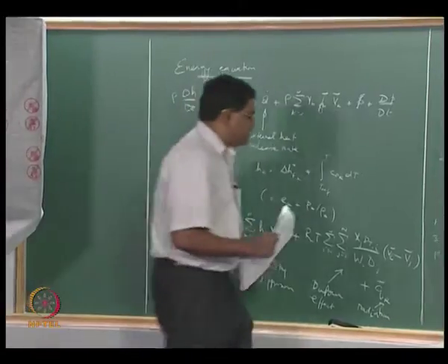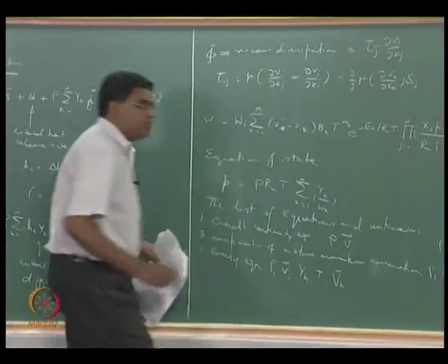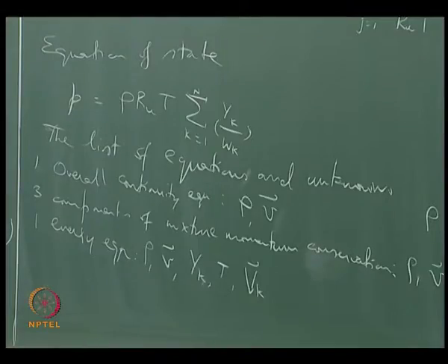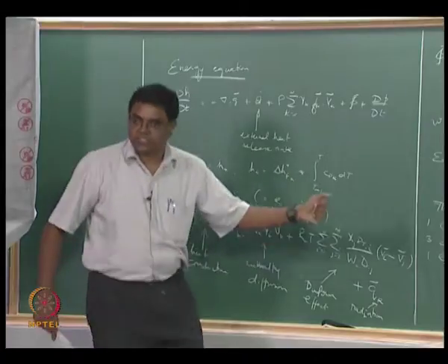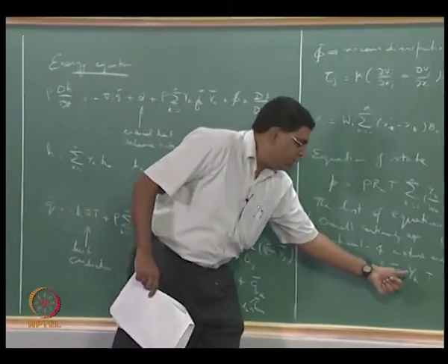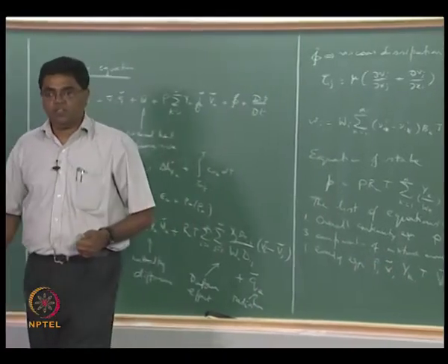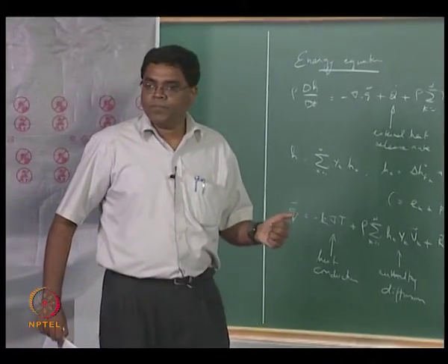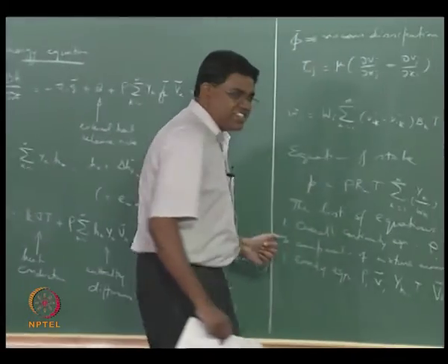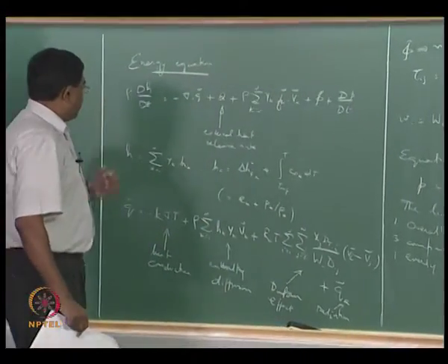Okay, that's a pain. Why is it a pain? It's n diffusion velocity vectors. That means there are actually 3n unknowns in 3D, for 3 components of each and every species diffusion velocity vector. So that's a lot of unknowns just proliferating by the minute with the energy equation. Looks like a big villain here.